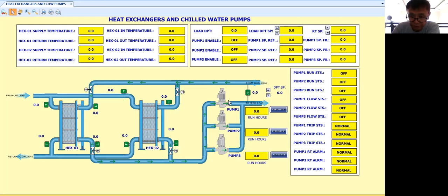So we are using that to monitor the flow, because maybe the motor of the pump is running, but we are not actually delivering water because maybe there's some problem with the pump's mechanical part, especially the impeller, which is responsible for delivering water, okay? Now, I don't have the start/stop command here, okay? Maybe I can include it also here, no problem.